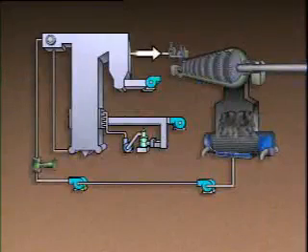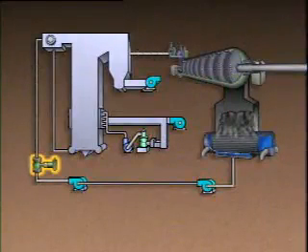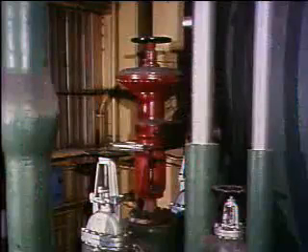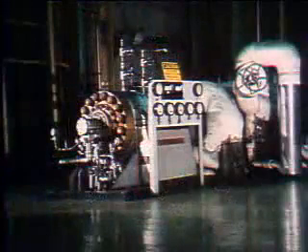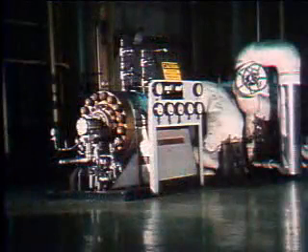When the steam flow is varied, the feed water flow to the boiler must be varied equally. In this system, feed water flow to the boiler is controlled by a valve in the feed water line going to the boiler. The feed water control valves are opened and closed to match feed water flow with steam flow. In some plants, this control is accomplished by varying the speed of the feed water pump. Other plants use a combination of both methods. Regardless of which method is used, the important point to remember is that steam flow and feed water flow must be controlled so that they're balanced.